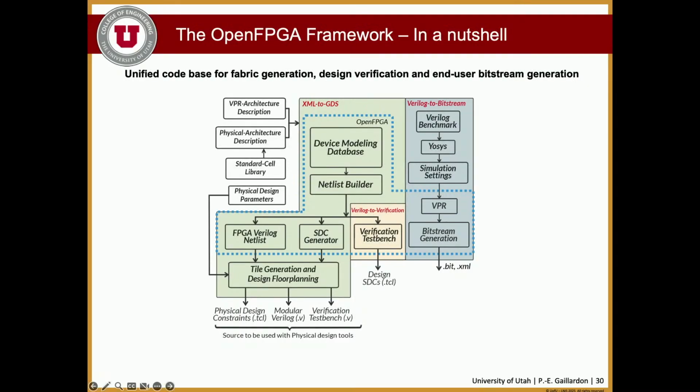And to do so, we took a software-centric approach. Interestingly enough, the first part of my presentation focused only on the hardware, and I just had one slide telling you that, oh well, the CAD tools need to support all of that. We took the exact opposite approach. What we did was create supporting software that is generic enough, so placement, routing, synthesis, the whole thing, that internally models any type of FPGA architecture you want through some high-level modeling. This is the topology I want.